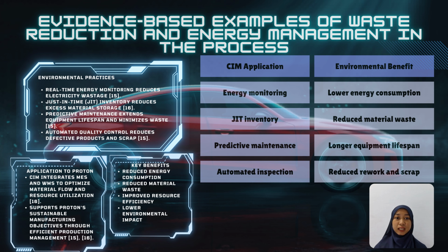Okay, next, this slide highlights how CIM contributes to environmental sustainability in Proton's manufacturing operation. Real-time energy monitoring helps reduce unnecessary electricity consumption, while just-in-time inventory management minimizes excess material storage, predictive maintenance extends equipment lifespan, and reduces waste generated from unexpected failures. In addition, automated quality control reduces defective products and scrap materials.